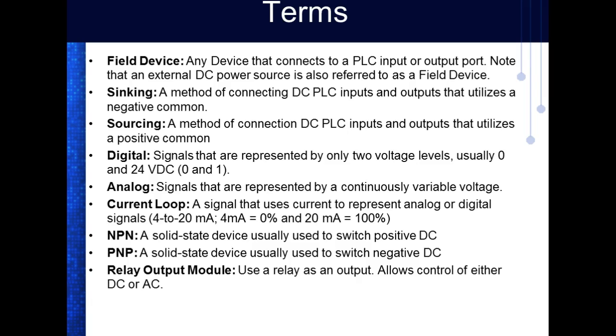So if you don't have broken wires or stuff like that, or if you don't exceed the voltage output of the amplifier, so the amplifier could only go up to 10 volts. But if you got enough resistance in there where it took more than 10 volts, then you have problems. But anything below that, now we use what we call a differential interface, which is also immune to noise. And it doesn't require current flow all the time. The biggest disadvantage of current loop is you always have current flow in your conductor. Current flow means power, it's not much. But, you know, if you've got 5,000 units out there running 4 to 20 milliamps, that's a lot.